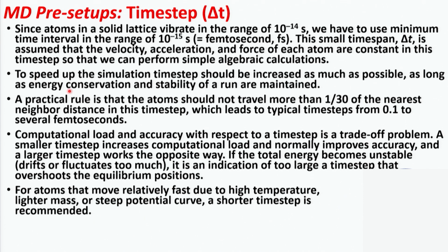Okay. To speed up the simulation, time steps should be increased as much as possible. If you increase the time step, then to get a certain time of molecular dynamics calculation, the number of steps will be less. Okay.